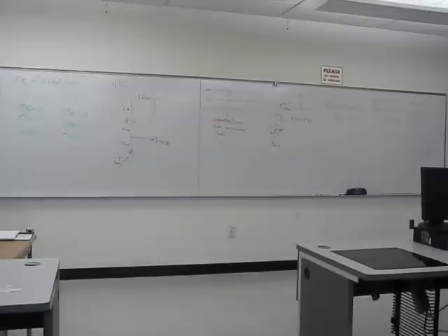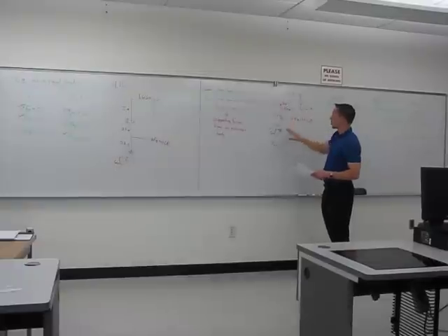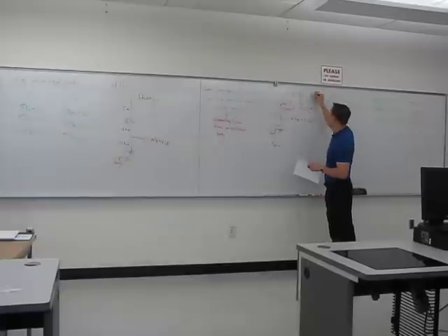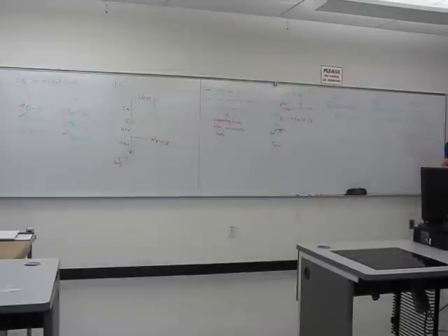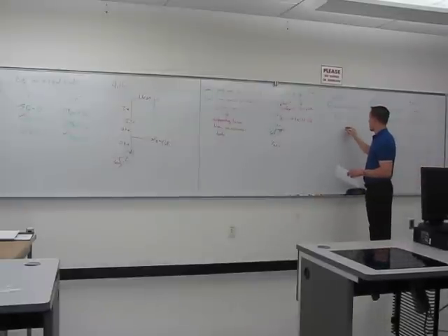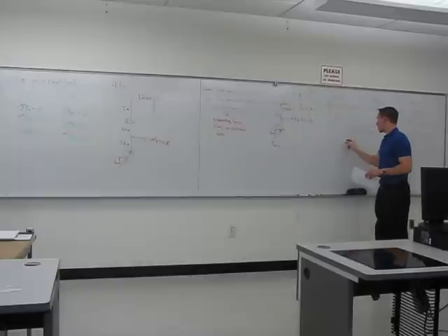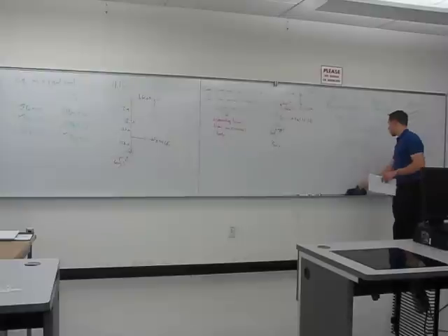But to express this as a vector, since there was no coordinate system given to us with this particular problem, we kind of were just assuming that we were using the standard, but that wasn't given to us. We should express this force Fc in terms of its magnitude and direction. So we're going to take here that the magnitude Fc is equal to the square root of negative 8 squared plus negative 0.93 squared. We'll take the angle to be the inverse tangent of the y component divided by the x component. So 0.93 divided by not 0.8, but 8 itself.